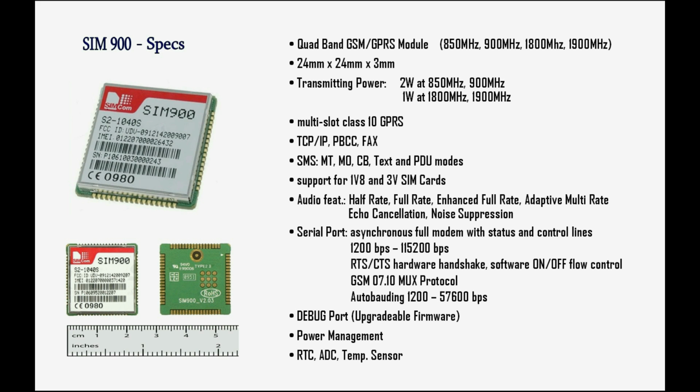It has an internal ADC which can be used to monitor the supply voltage, and an internal temperature sensor. It supports an RTC, however I used a dedicated chip for the real-time clock. It has different operational modes which can be used to efficiently control the power consumption. Most of the hardware control functions can also be implemented in software by using dedicated AT commands.